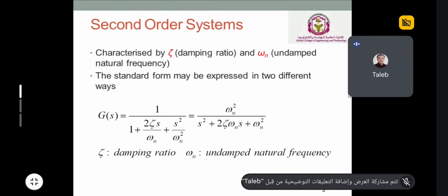So here we have some new concept, because the output of the system is not that smooth going up. It has some oscillation. We say damping. We have some vibration, some oscillations with some frequency. So we have natural frequency or undamped natural frequency. When it is under damping, we have some frequency of damping. How much the system is oscillated, how fast, is determined by omega n.